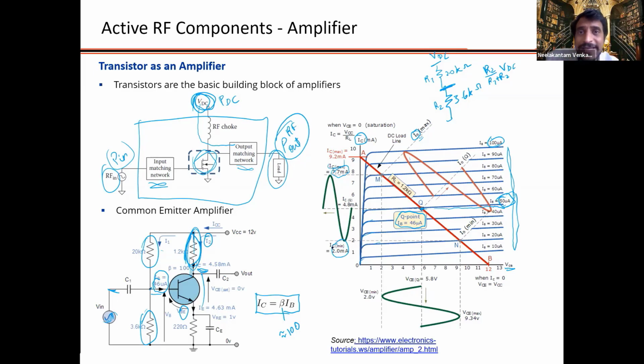So you got a gain there, right? When I inject a voltage signal like this, my base current is going to change, swinging in microamperes. I got a 1,000 times factor in terms of milliamperes here. And that milliampere current, when it goes through the load line, where the load is 1.2 kilo ohms, you're going to get a sufficient voltage output that is going to swing much higher in power. So that's essentially the working of a transistor as an amplifier.